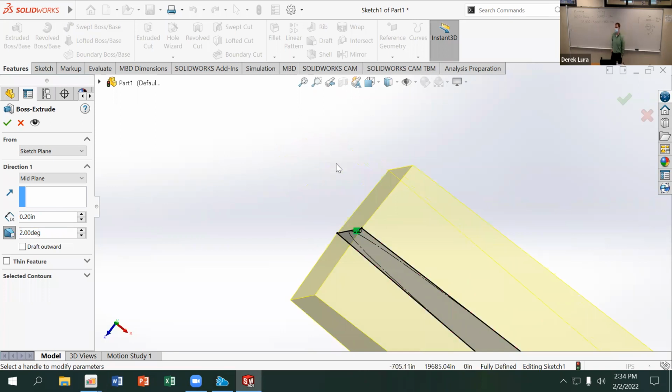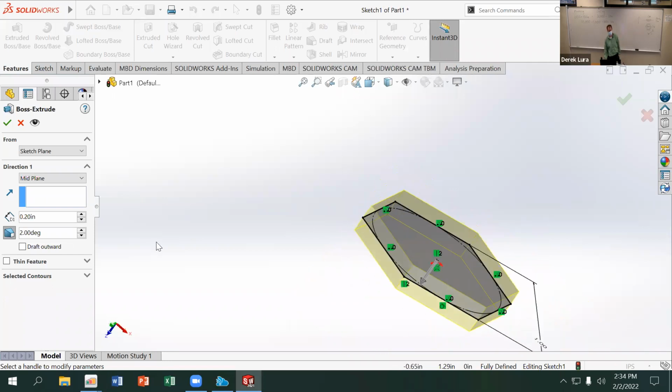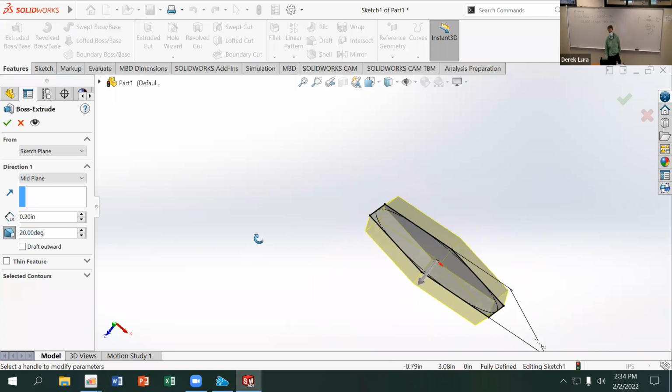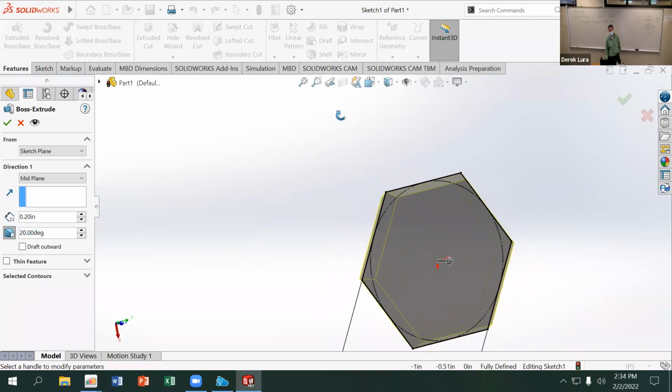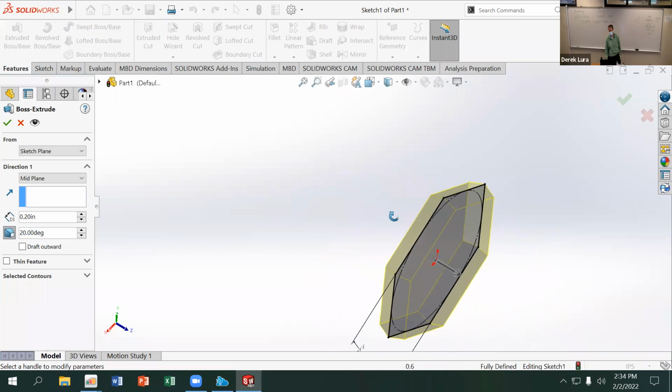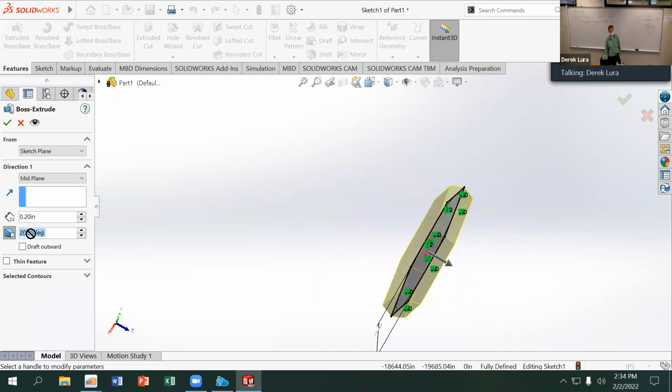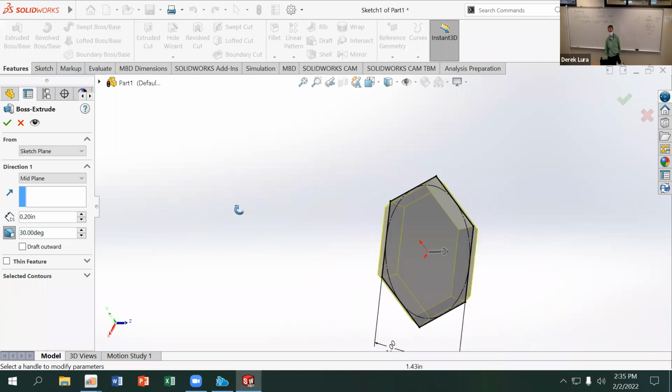So you guys have probably seen a lot of injection molded parts that don't look like they have a draft angle because 2 degrees is really small, right? But most parts, that's enough. Now, in this case, I want that draft to be part of a decorative feature for my part. So 2 degrees is not sufficiently obvious. I'll try making it 20. And now you can actually see that, okay, that's got some angle to it, right? And if you want to make yours bigger, you want to do 30 or something, right? It doesn't matter. We're just doing this for fun, please.